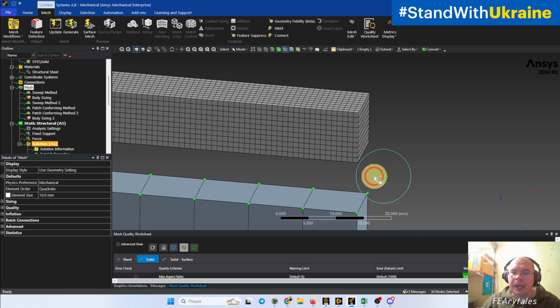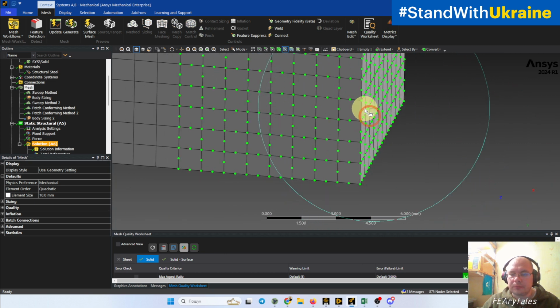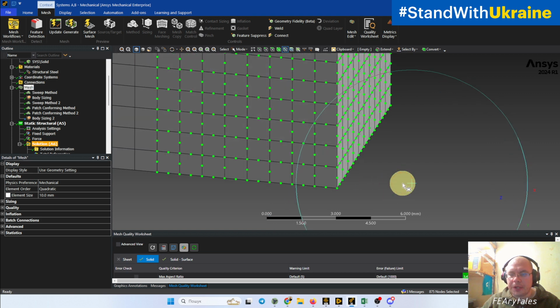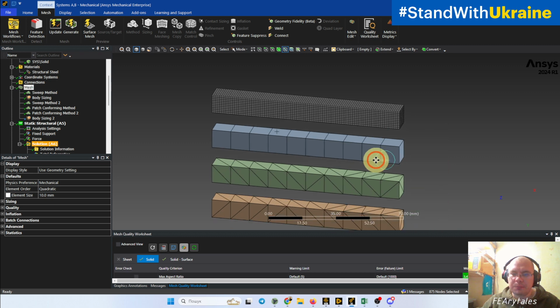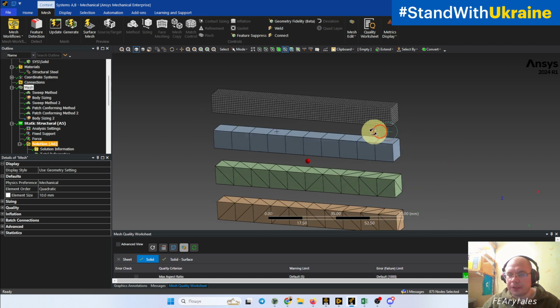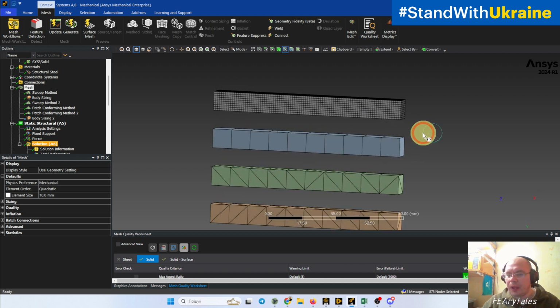As an accurate and tolerant solution, we will use a beam meshed with hex mesh, and this mesh not only has 10 elements per side and 100 elements per length, but is also a quadratic element with mid-side. So these bars are 100 millimeters per length and 10 millimeters per side.